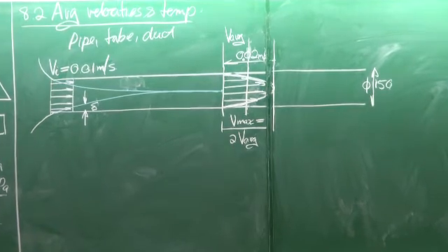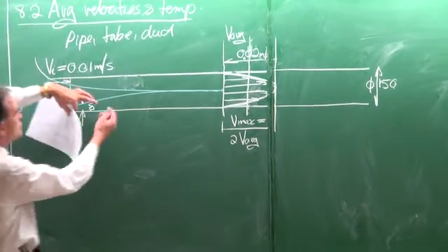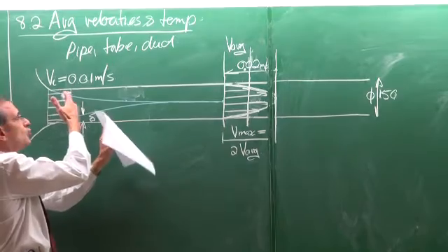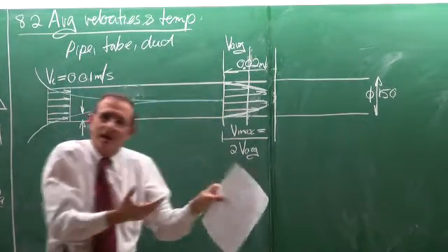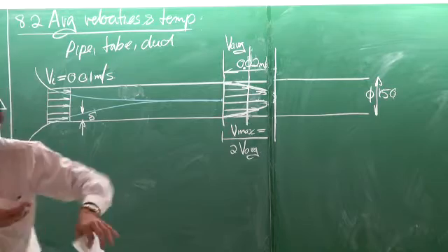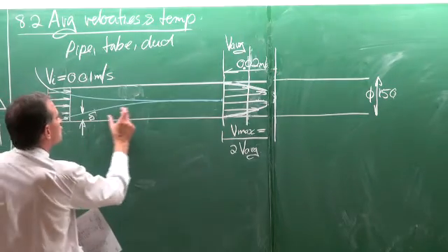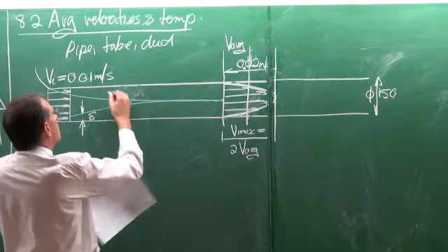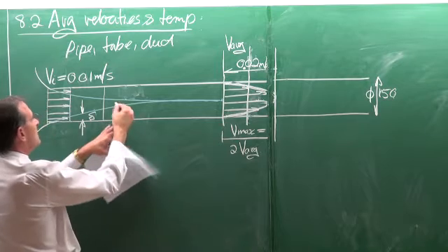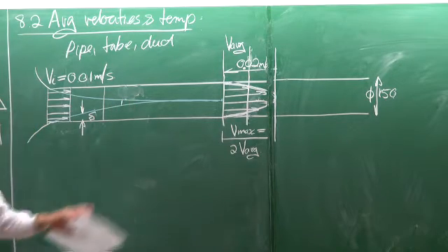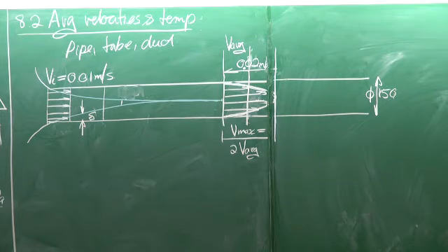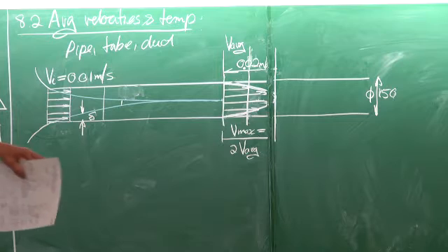Okay, so what I start with here, because of the fact that continuity must still occur. I mean, what you're putting in must come out. And that mass flow, now because of this change in the boundary layer, so what is going to happen here? In this part here, you're going to get the part which is irrotational flow. Irrotational flow. There are no other forces. It is like ideal flow. It doesn't even know about the boundary layer.